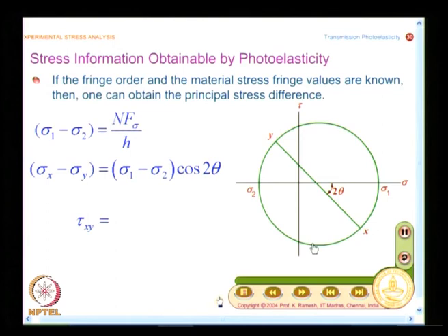You can find out what is the normal and shear stress, absolutely no problem. So, that is why it is a beautiful representation. I do not know whether you looked at Mohr circle from this point of view. When I said all the possible states of stress in all the infinite planes at a point of interest, that is what you understand as the stress tensor, and a beautiful graphical representation is the Mohr circle.